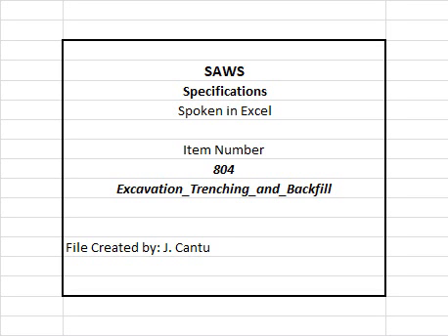B. All excavated materials not required or suitable for backfill shall be removed and properly disposed of by the contractor or as directed by the inspector at no additional cost to SAWS. C. Grading shall be done as may be necessary to prevent surface water from flowing into trenches or other excavations, and any water accumulating therein shall be removed by pumping or by other approved methods. D. Sheeting and shoring shall be installed in accordance with all adjoining property, and for the safety of all personnel.